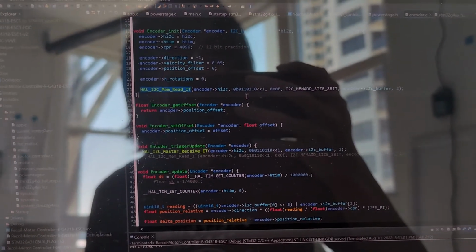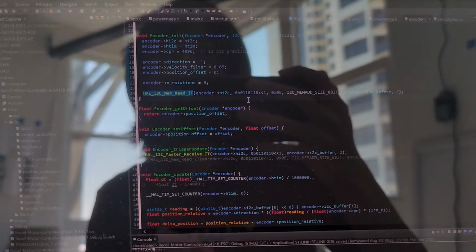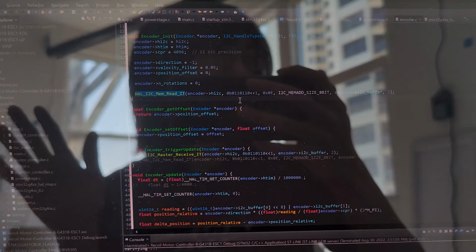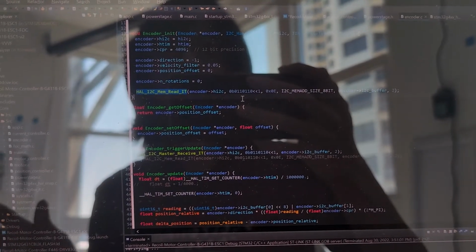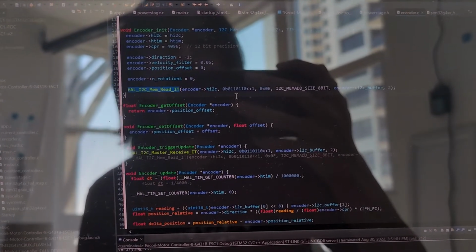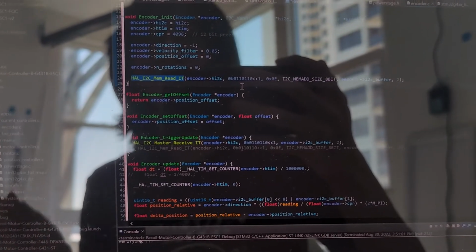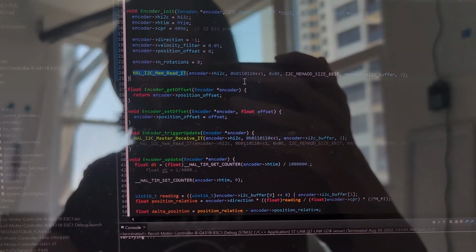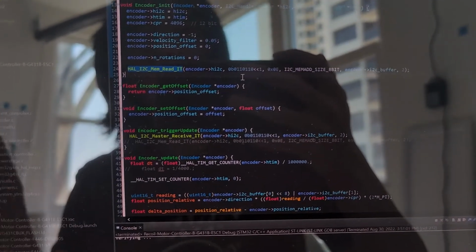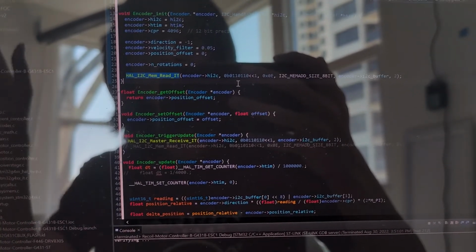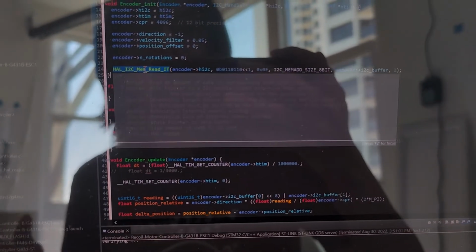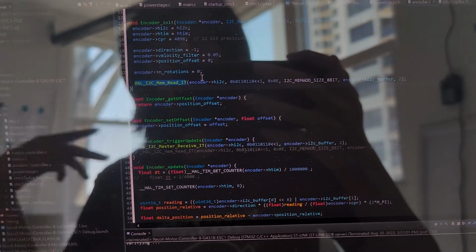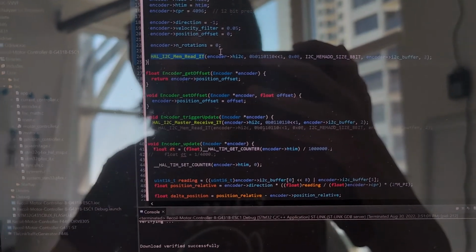So to change that, fortunately the AS5600 encoder supports storing that configuration register address inside its own memory, so that during the initial setup we can issue a memory read command, and then we just need to continue sending the pull command.